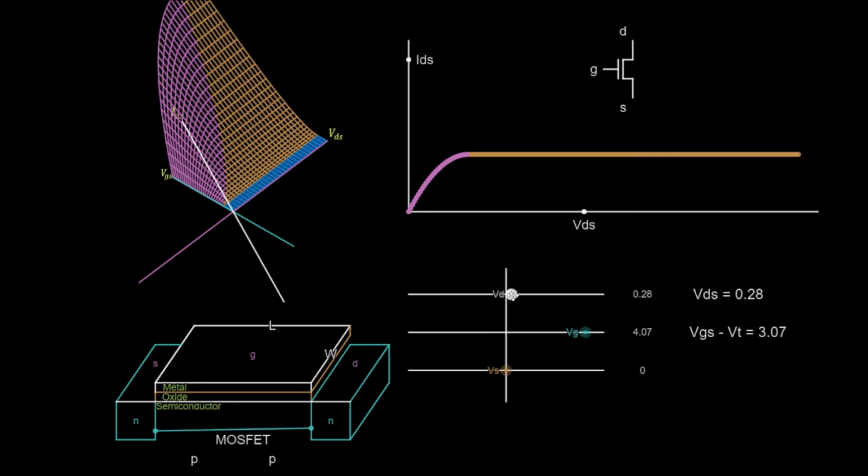And you can see the drain voltage here adjusting, and you can see the depth of the inversion layer changing, until we get to a point here where we get a pinch off. So the point here, we get a pinch off when our VGS minus VT is equal to the VDS, and at this very point we'll be at this corner of the curve, and after that we'll move into the saturation region, and the saturation region will be up along this section of the curve here.